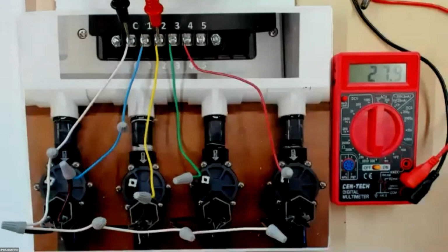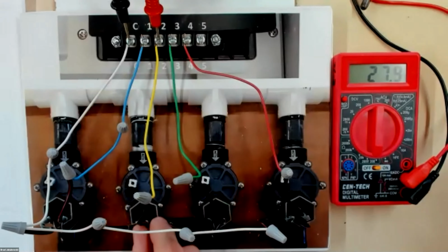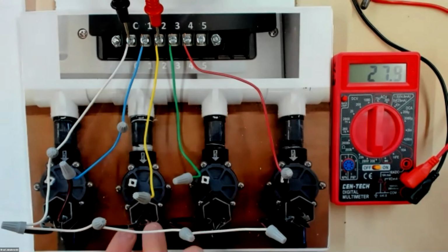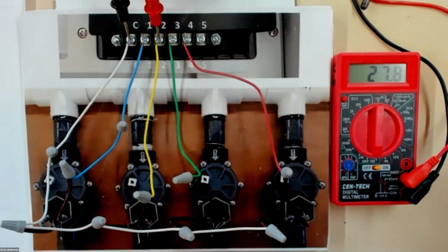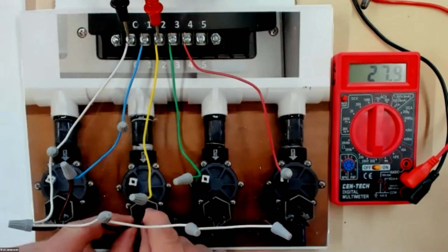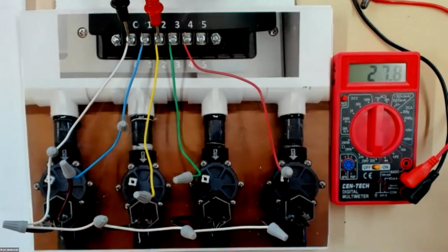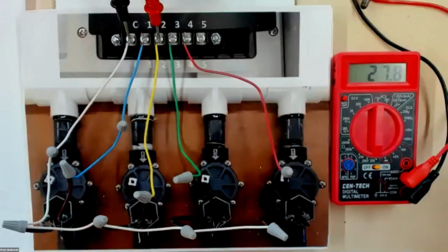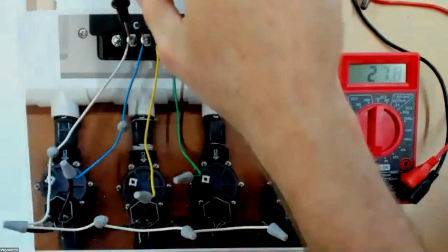Yes, that got me 27.6. Perfect. Okay, so the resistor wires and the speaker wires are just being held together by the heat shrink right there. Sometimes they might work their way a little bit loose. If you need to, just twist those wires a little bit, and you should be able to get continuity back. I'm glad it's working. Actually, I'm glad somebody had an issue so we could go through that together. Excellent. Okay, moving on to number 3.